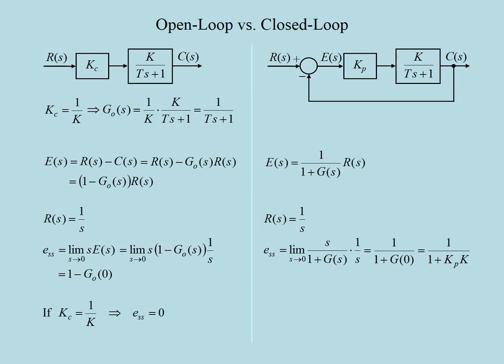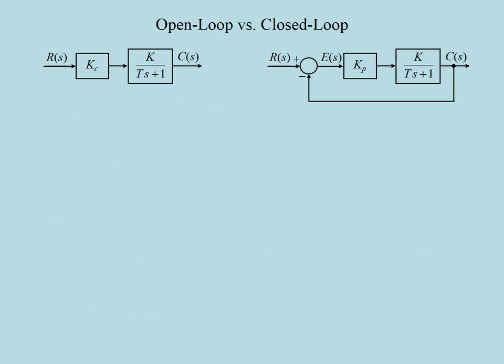This result is in accordance with the fact that proportional control action must result in non-zero error. It is true that at the expense of increasing Kp, you can make the error as small as you wish, yet an ideal cancellation of the error is not possible. Well, does this mean that the closed loop operation should not be favored against open loop? Before making our minds up, let us consider another and more realistic scenario.